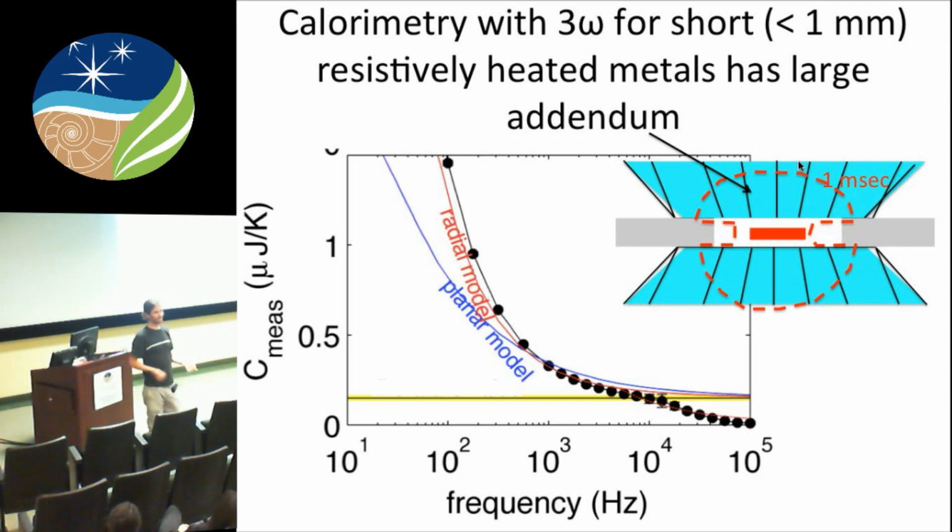Harmonics can be generated in many places in a circuit. It can be generated in the place I want it to be generated, which is at the heater, or it can be generated in the amplifier, in electrical contacts. So the frequency dependence of each of those potential sources of harmonic generation is mysterious. Yeah, Steve? Are you using a reference voltage? What's that? A secondary reference voltage, and then comparing the two voltages against each other. You should be able to subtract out any non-specific harmonics if you use a reference voltage. Yeah.